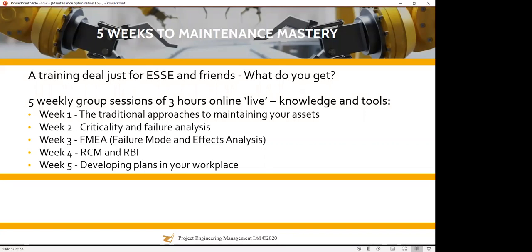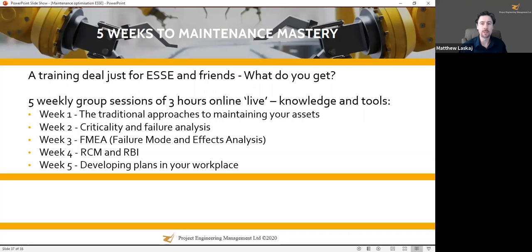So I've put together 3-hour sessions over 5 weeks where we're going to cover the traditional approaches, so reactive, planned, predictive. Then it's all about analyzing the failure and the criticality, and risk ranking criticality using what we call FMEA. Understand how you can then use the RCM process to prioritize your tasks and pick the right tasks.